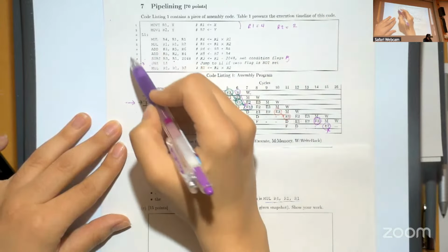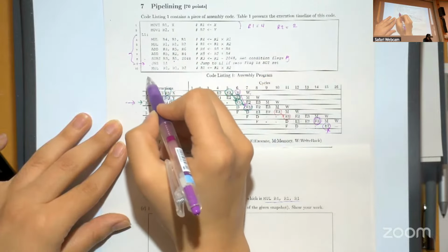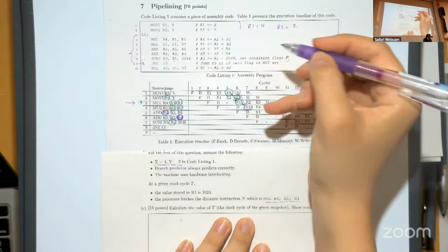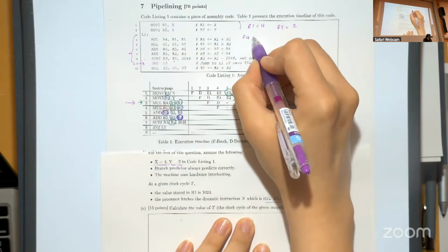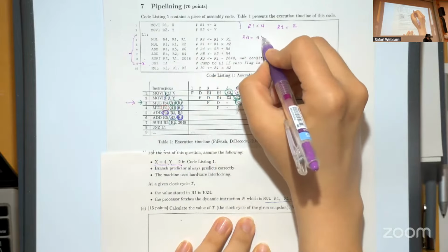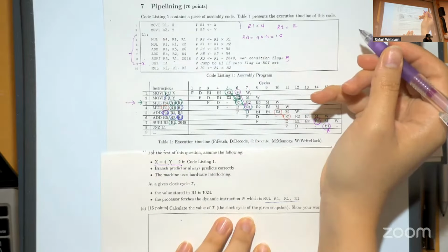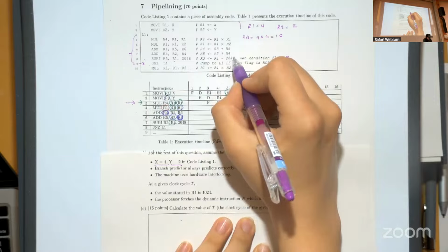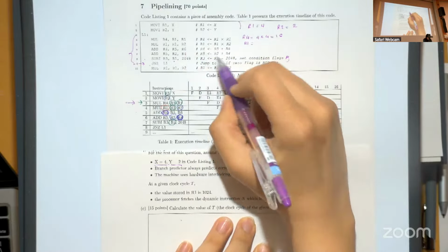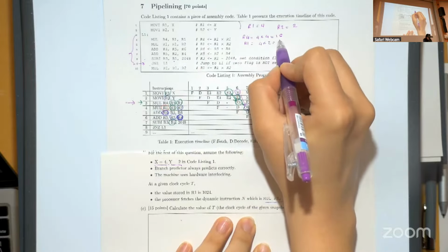And inside the loop, so this is like a loop. As you can see, there's a jump to the start of the loop. The first instruction does the following. It writes to R4 by multiplying R1 and R1, which is 4 multiplied by 4, and that is 16. Is that correct? Yes. And then in the second part, it updates R1 by multiplying R1 with R2, which is 4 multiplied by 2, which is 8.